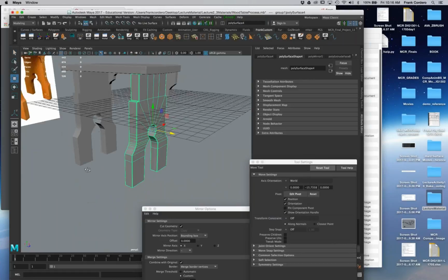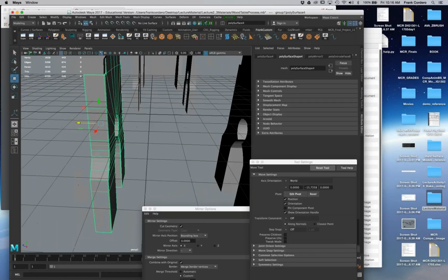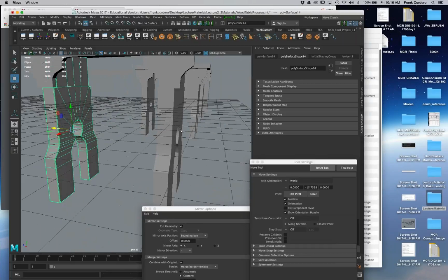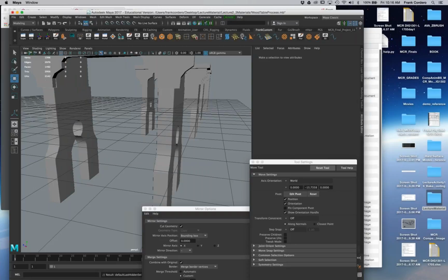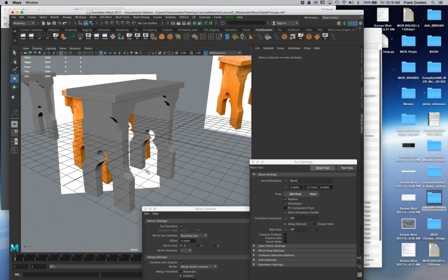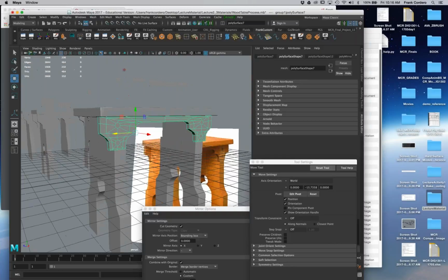What's the point? So let's go ahead, Command D, middle mouse button V. Let's duplicate this shape. And then I'll just use this piece as a guide, hold down the V key. There you go. Control H temporarily gets rid of this one, and then Control Shift H brings back my selected piece. So again, we're progressively finishing the model. Now I want to deal with this stuff.